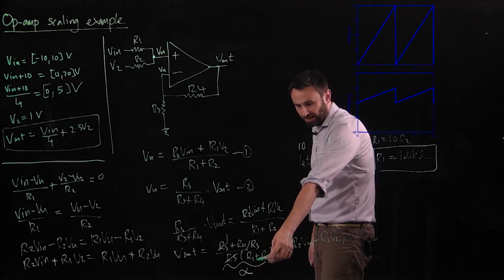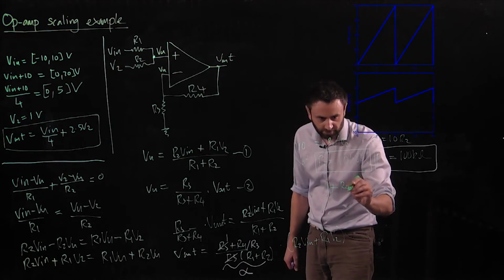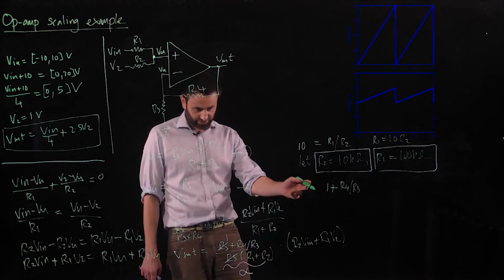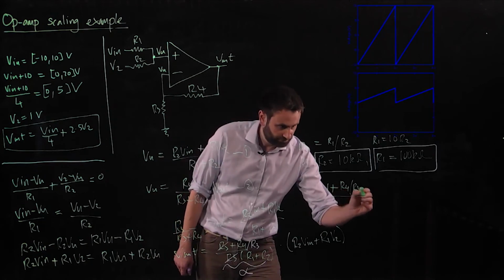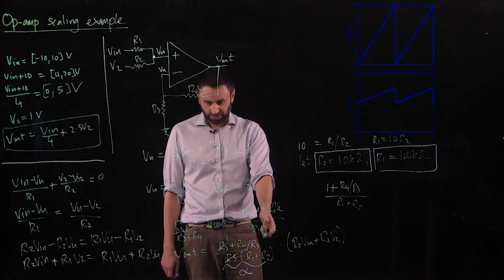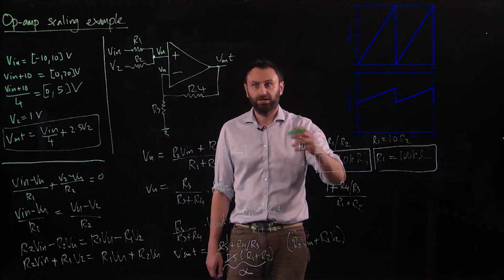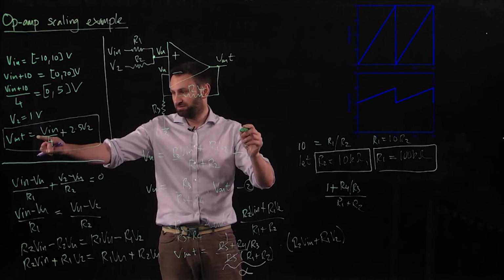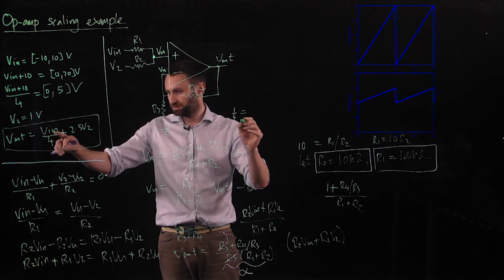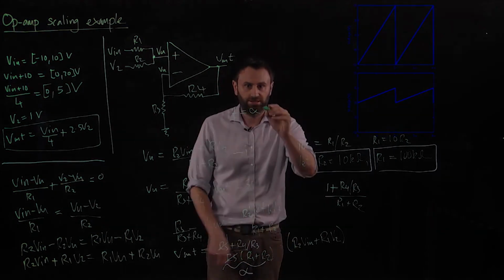Let's start with what we have down here for alpha, which once it's cleared up a bit is 1 plus R4 over R3. And that's divided by R1 plus R2. That's alpha. And we know from, I'll have to pick one of these equations. So let's use the equation that I just had up there. I'll rewrite it over here. So when we compared the coefficients of V in, we had 1/4 equals the same coefficient of V in down here, which was alpha times R2.